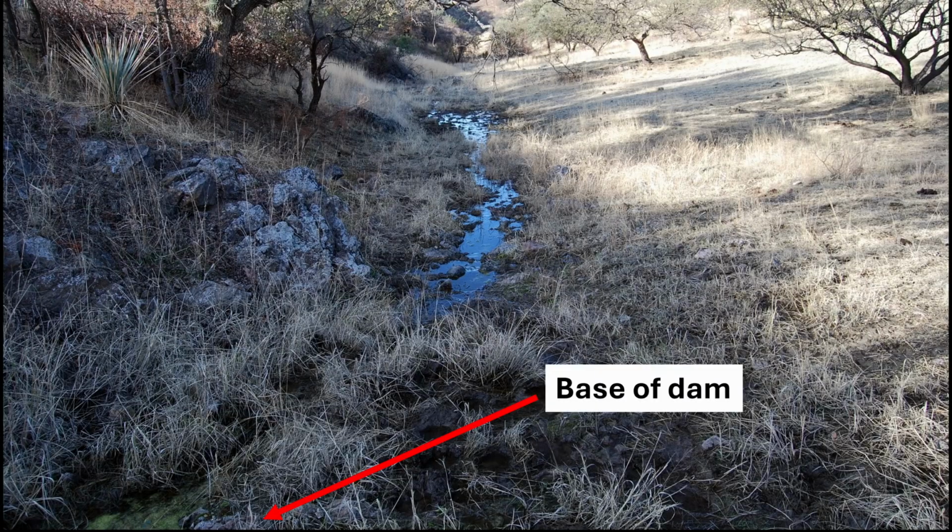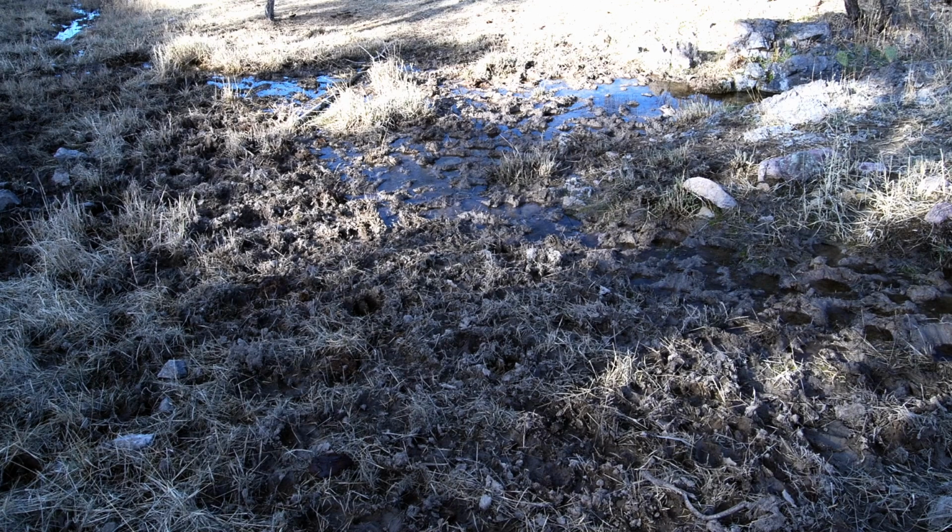The red arrow points to the outside toe slope of the constructed dam. The stream is emerging like it's a spring under the dam. The flow of water is not from the spillway. This stream shows that water is flowing under the dam, explaining why the pond only holds water after infrequent and heavy rains. The mud area and water you see in this photo is within sight of the backside of the dam for a pond that contains very little water.